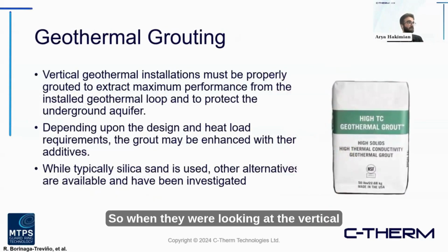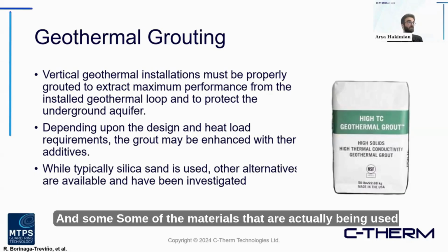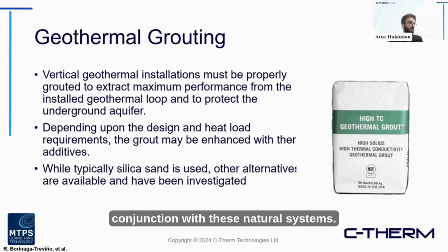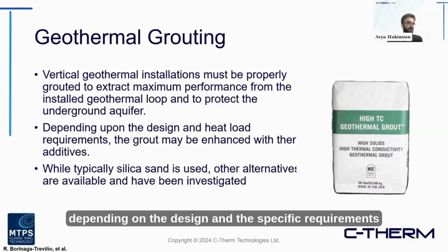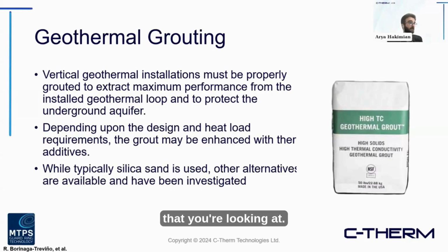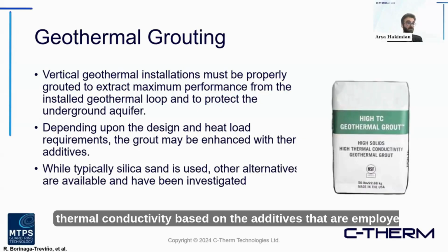So when they were looking at the vertical geothermal installations, one of the considerations involves some of the construction and some of the materials that are actually being used in conjunction with these natural systems. So there is a geothermal grout that is employed. Depending on the design and the specific requirements, these grouts can enhance the thermal conductivity based on the additives that are employed.